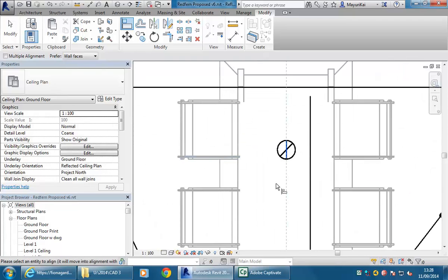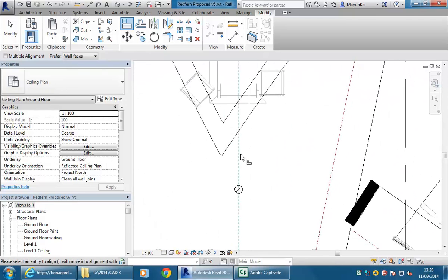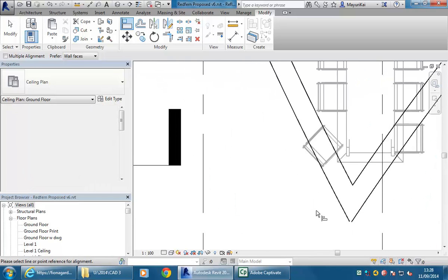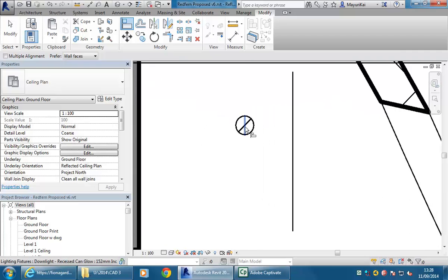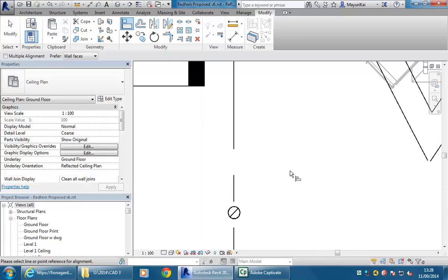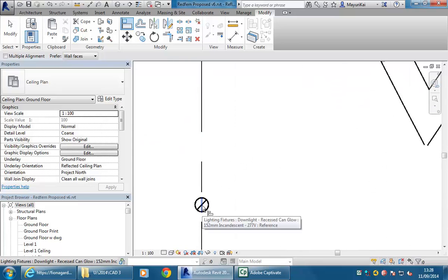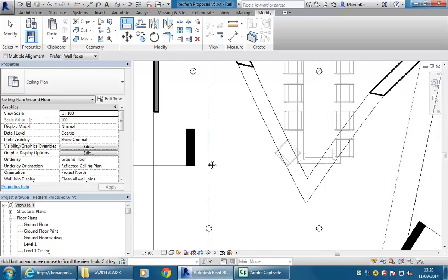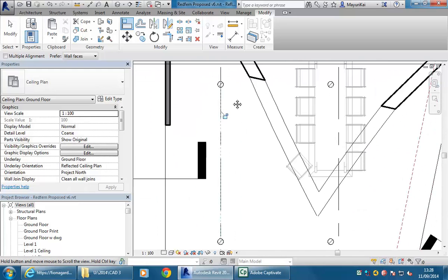And so if you're not using the Align tool very much, just make sure again you realise that you can always reset it by clicking into a blank spot, and that'll let you choose a new edge. I actually want to go the other way, so this one, yeah, and then this one.